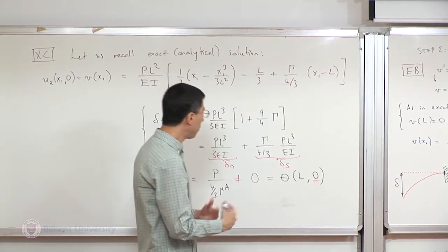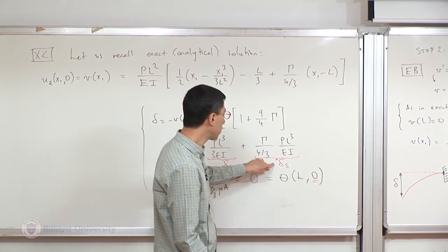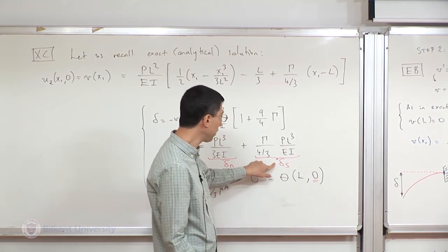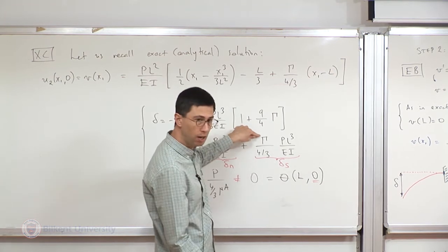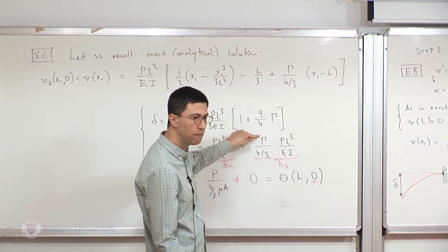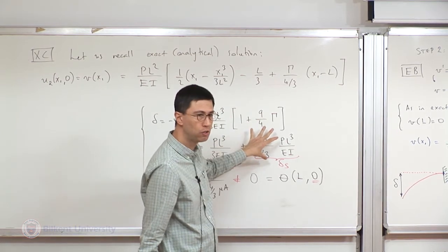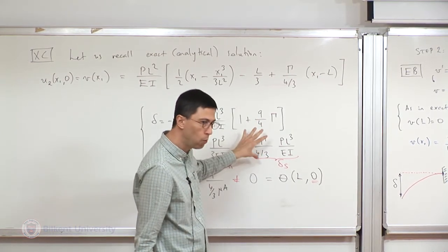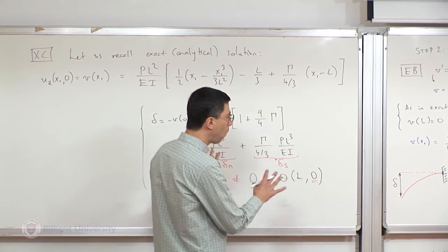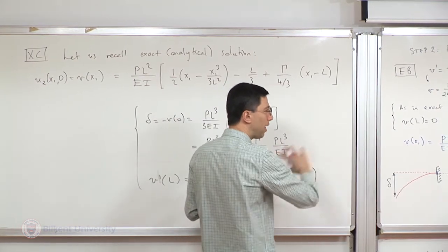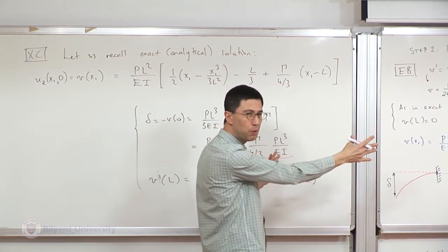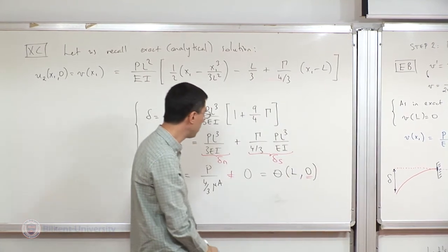Okay? And at that time, I had said, well, there's a second term. That term diminishes with h over L going to 0. Now we see it, because now I have this factor that I discussed, gamma. And I had said that that term has to do with the influence of shear stresses. Now we understand why. But now what we can also do is compare our solution with the Timoshenko beam theory. And we see something remarkable, actually.